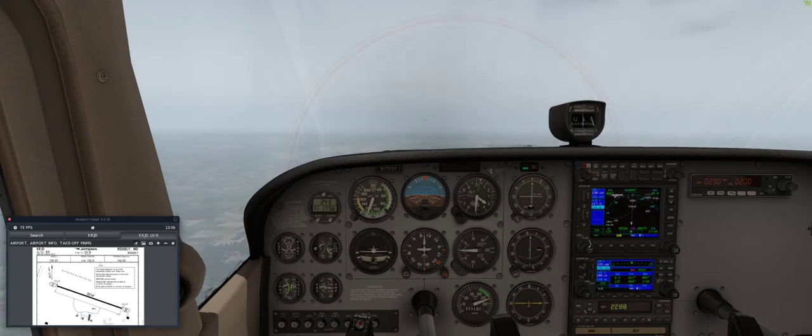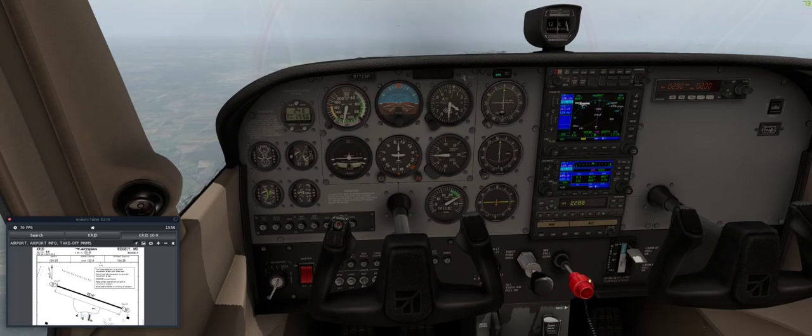And since we leveled off, I should have been monitoring engine RPMs and keeping this out of the red, which I did not, so I just abused our aircraft, our engine a little bit there. And if it had happened to overspeed, I'd have done even more bad. And I said earlier I want to look at trend, look at mixture again.